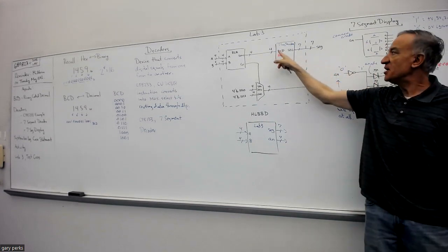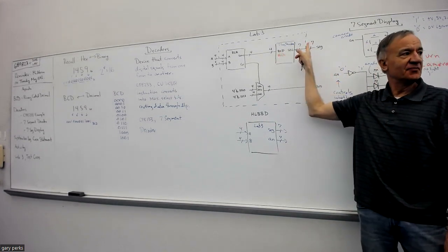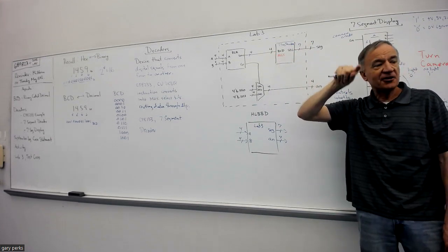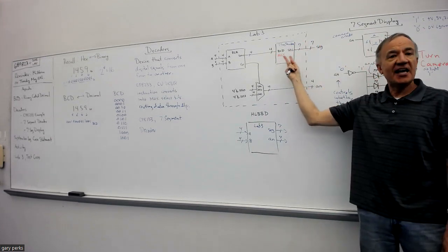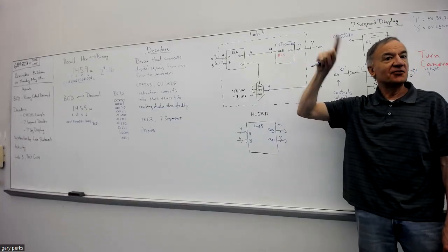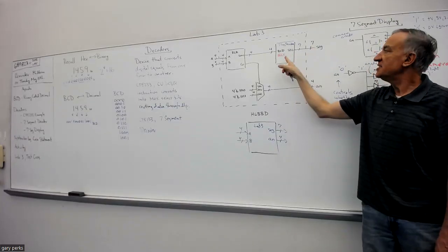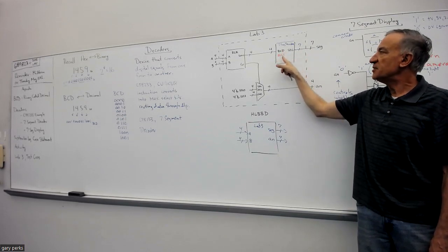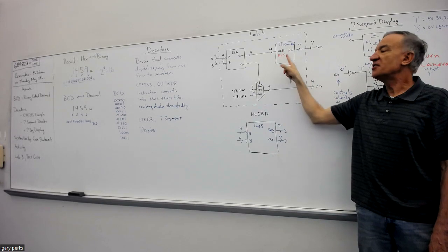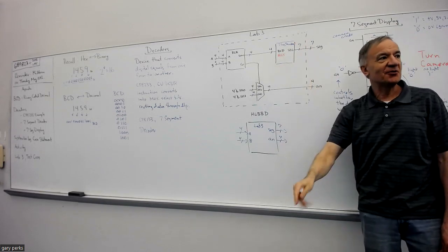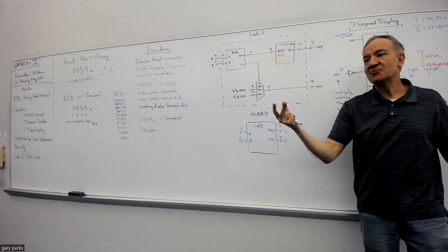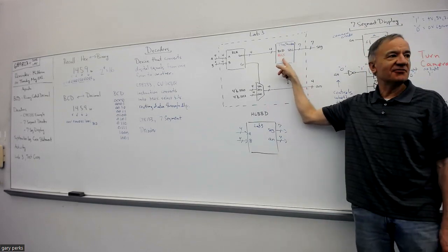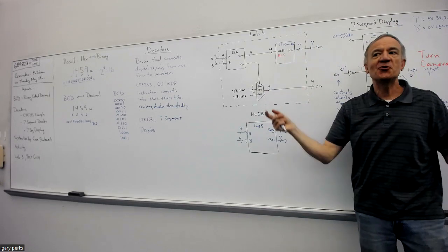So we can have this be a BCD decoder, that takes this binary and shows decimal characters 0 through 9, or we can make it a hex, which shows 0 through 9, then A through F. So the only difference that you're going to see in a moment between having this BCD and this hex is that with hex we'll have a bigger truth table, because you've got more characters in base 16 than you do in base 10. Okay? So that's why I'm changing this from BCD to hex, because it's a little bit more interesting.